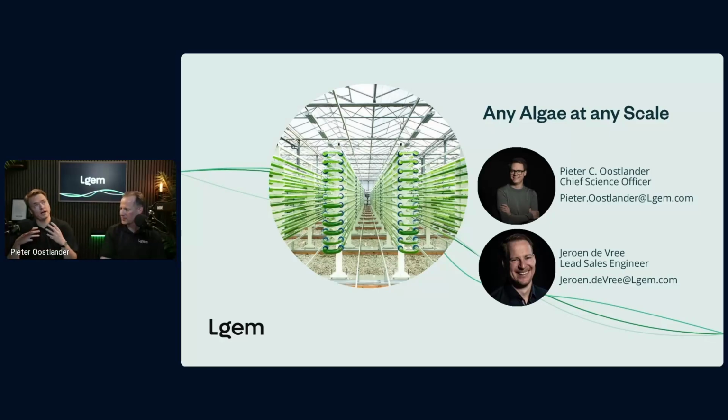By having enough movement in the reactor and enough turbulence in the tubes, the algae cells on the outside will quickly move to the inside and the light will be distributed over the volume that way. Another way to think about it, if we run chemostat experiments, the culture will find the balance of how fast it can grow given the conditions of light, dilution rate, nutrients, those kinds of things. So you will find the productivity that is the sweet spot for the culture with those light conditions.